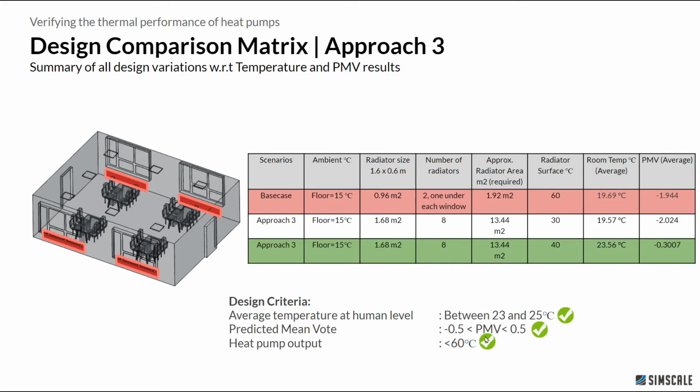And hence, this can be justified as an optimal design that can be used for this particular indoor space. This way, we will be able to make the concept phase validated using CFD so that you can easily pick up the optimal design for your heat pumps, and also the number of radiators or the surface area of the radiators can easily be tested, and all these concepts can be validated.